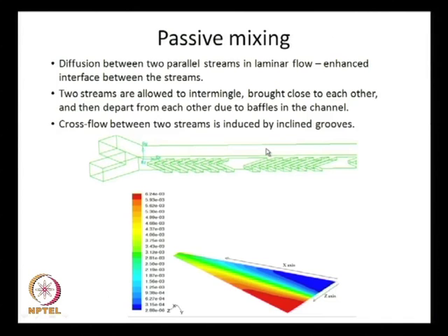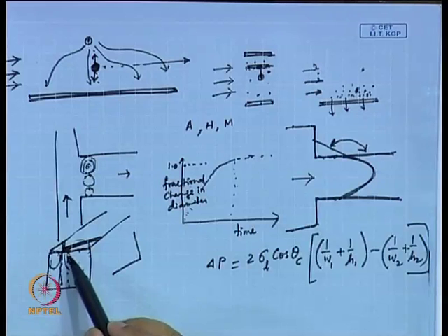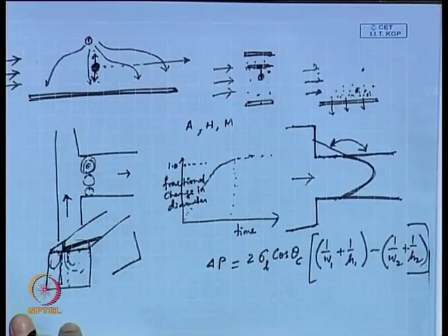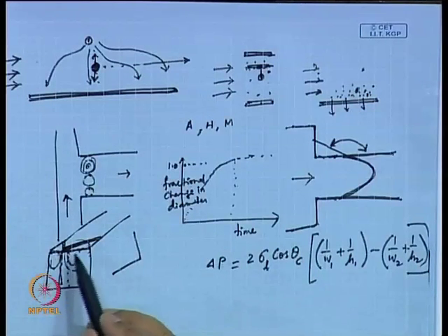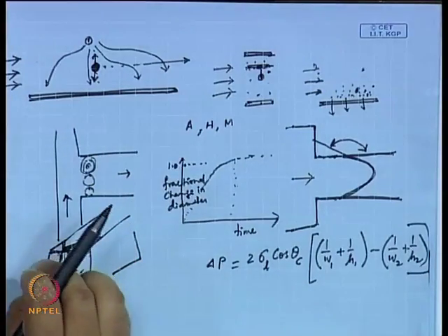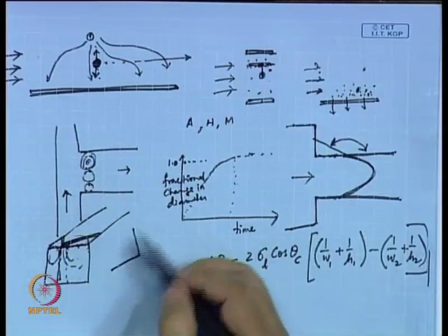So, earlier you were swirling with the 2/3 portion of this. Originally, the fluid that entered was split half to this side and half to that side. However, you started working with 2/3 on this side and 1/3. So, you picked up a certain portion from this and you are putting it into the other stream, and then after 5 such grooves, you are reversing the flow pattern. So, by this way you are having cross flow, then again moving in the other direction. At the end of it you are accomplishing a thorough mixing, that is the whole idea.